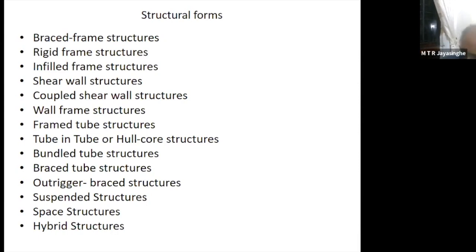The slab does not know that there's a drop. So basically, you will not go for 5 meter or 6 meter spans. You will go for 8 to 10 meter spans, knowing very well the use of 225 to 230 millimeter slab will allow you to have all the washroom drops within the slab. Have I answered the question?